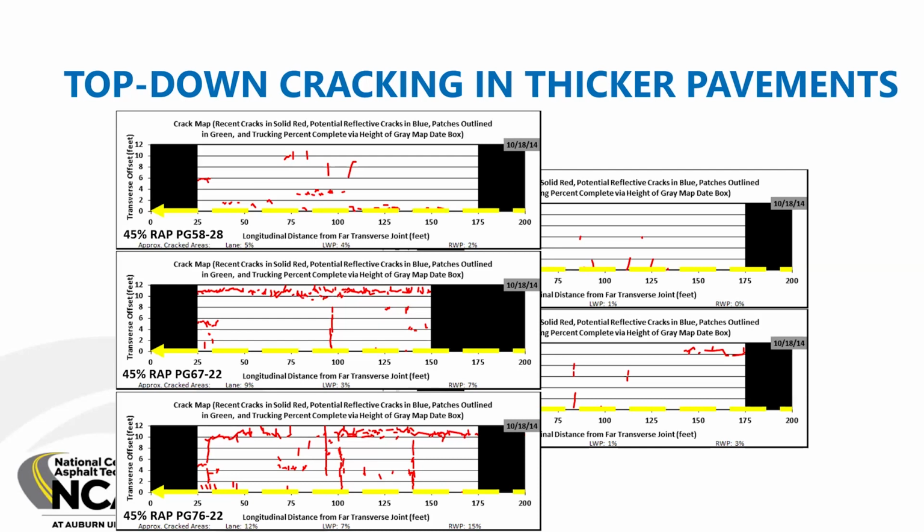So to back up and give you a summary of all that, when you see longitudinal cracking, cracking in the direction of traffic, and it's in the interior of the wheel path, near the middle of the wheel path, then that's an indication of bottom up fatigue cracking, or possibly middle up if you've had some debonding in there. But when you see longitudinal cracking along the outside edges of the wheel paths, that's an indication that might be a perpetual pavement, and that might be pure top down cracking or near surface cracking.